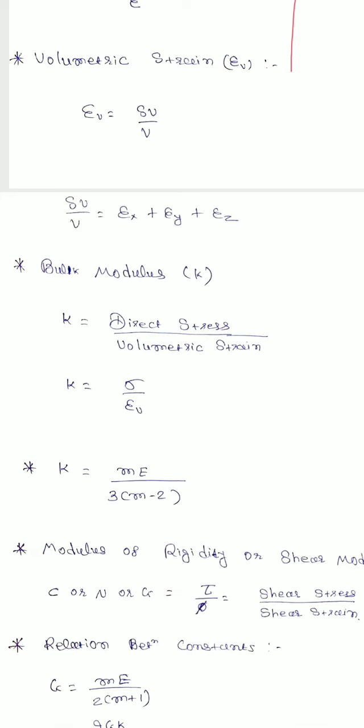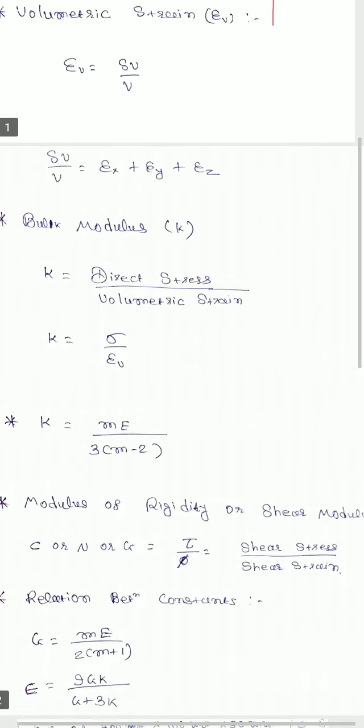Now we will use another term. It is known as modulus of rigidity. We already know modulus of elasticity. The modulus of elasticity will be used only for linear stress or strain, or axial stress or strain. But if we use shear stress or shear force, then we have to use modulus of rigidity or shear modulus.